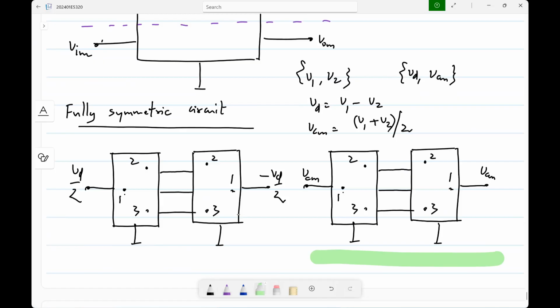The corresponding node voltages here and there will be the same, and the currents flowing through these wires will be 0. Okay. In fact, you can imagine that by first removing these wires, and then you will get some solution to these two. But of course, the voltage here and there will be the same. Then you connect them, nothing happens. Okay, so no current will flow. So you can analyze this by just cutting off those wires and analyzing only the half circuit.